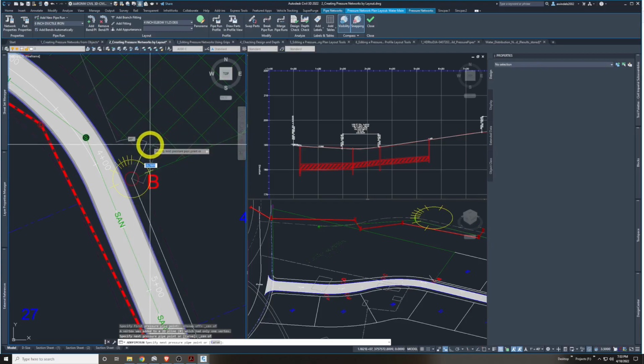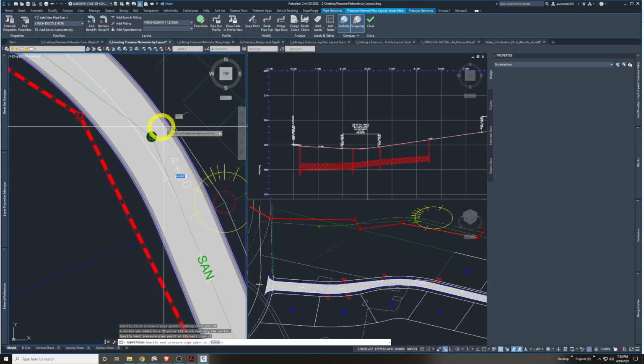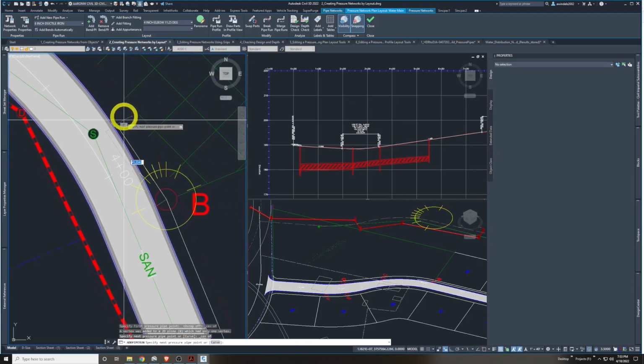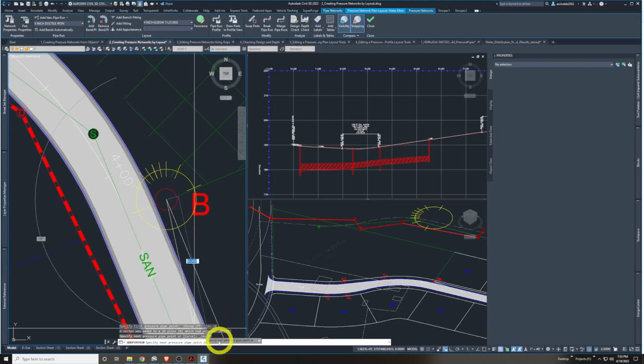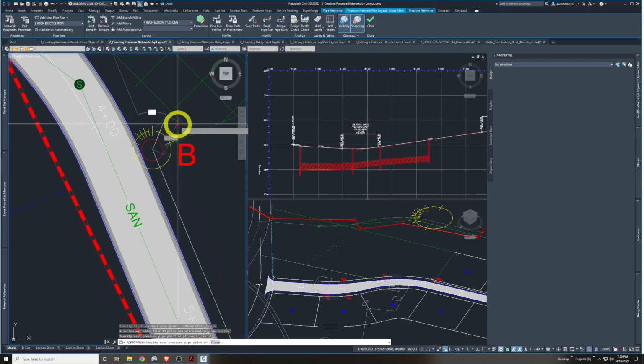This lets us design a little more dynamically, so we don't have to sit here and do these manually one at a time. That is a pain to allow the deflection angle of this amount of pipe. Or at this point on the command line, you could tell it to be a curve as the next available option. We'll hit curve. Okay.